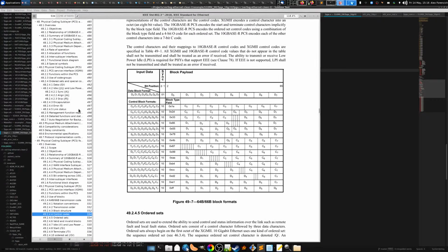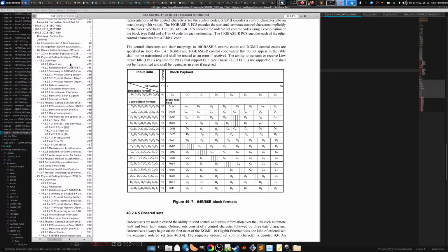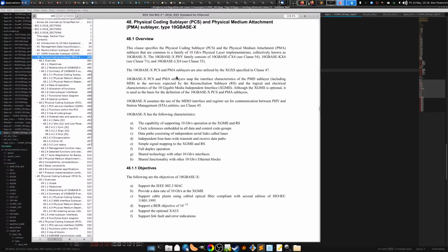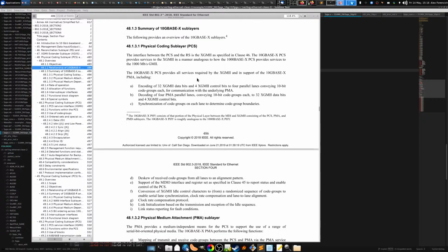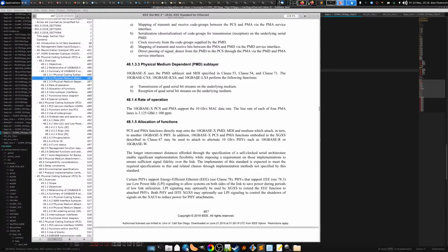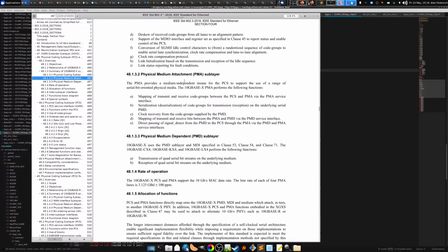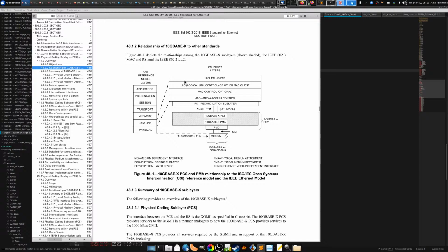So the thing to keep in mind with Ethernet is there's a whole bunch of different variations. I think the original version of 10G was this thing called 10GBASE-X, and this is not what we're implementing now. Need to take a look at this and make sure. Yeah, okay. So as Ethernet was developed, they started doing stuff over fiber. One of the first fiber, maybe not the first one, was called an SFP module that runs at a gigabit per second.